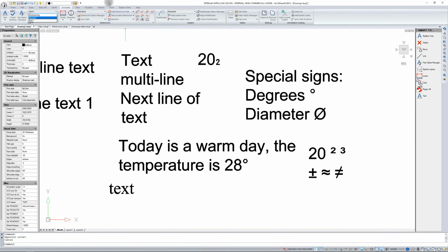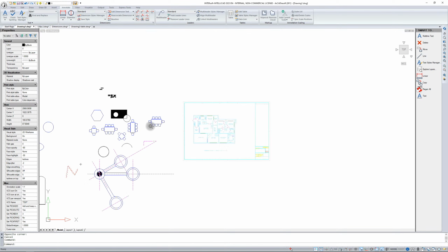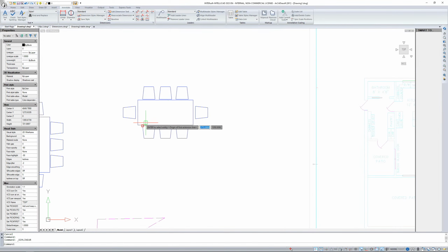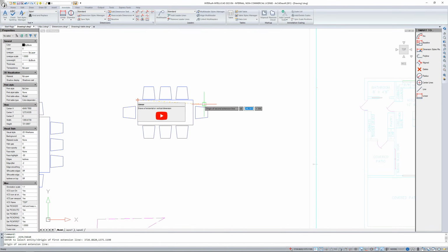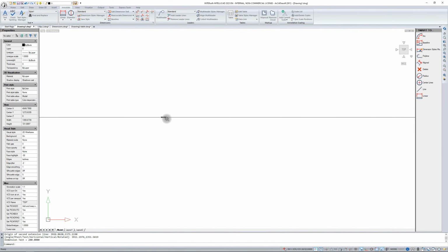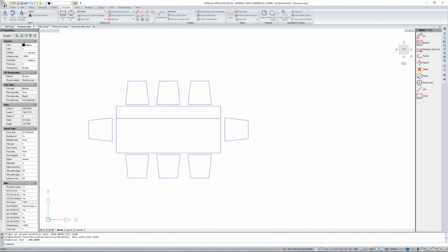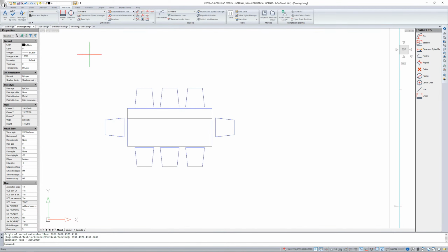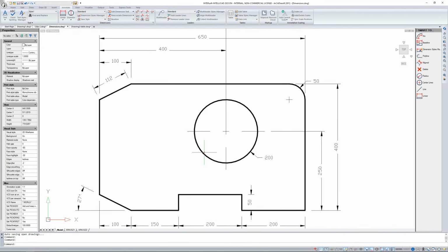So let's move on to the dimensioning. I will show it on some element introduced here. You should start by entering the Dimension Style Manager window. Why? I'll show you. When I enter any dimension in the basic default settings, you can see that the text is tiny. As in the case of entering the default text of this single line text, this value is quite small, so it may happen that again you will only notice the line. That's why I'll leave it for now. Later it will be modified with what I'm going to change in the style here.